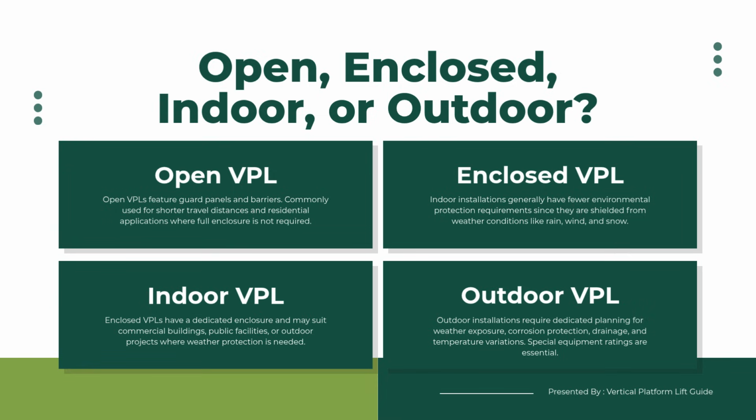6. Self-supporting elevator shaft. Structural limitations are another common challenge. An elevator introduces new loads into the building, so engineers need to evaluate foundations, floor slabs, anchoring points, and load transfer paths. If the existing structure cannot easily support a conventional shaft, a self-supporting shaft may be considered.